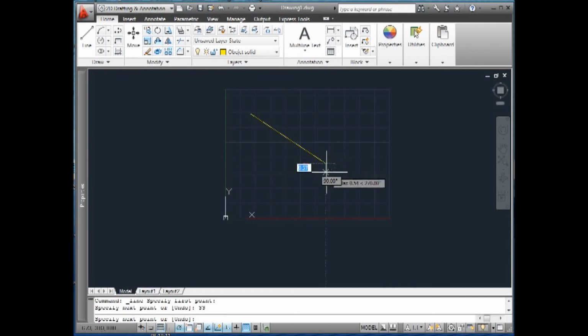The length of that line is determined by how far I've dragged it, so it's not real accurate in that sense. I'm just showing you a little bit about how to draw. This is not drawing with accuracy, this is just a pull, point, and click kind of drawing. The length is the first thing showing up in blue. All I have to do is hit my tab button and I'm sent back to angles. If I hit tab again, I'm back to lengths. So I'm going to type in 2.5, enter, and it draws a line that's 2.5 units or 2.5 inches.